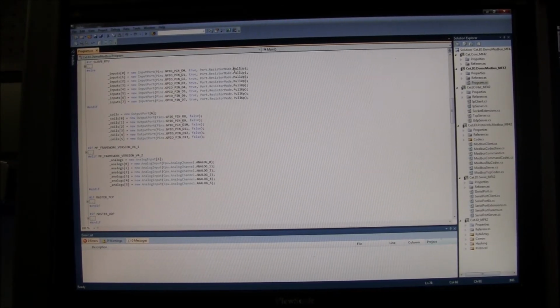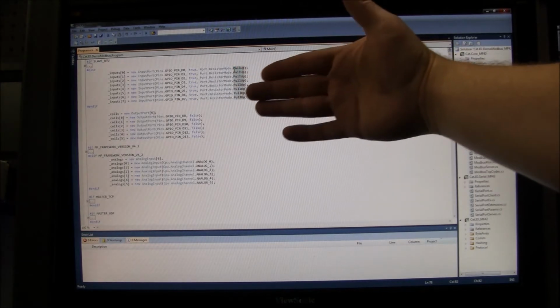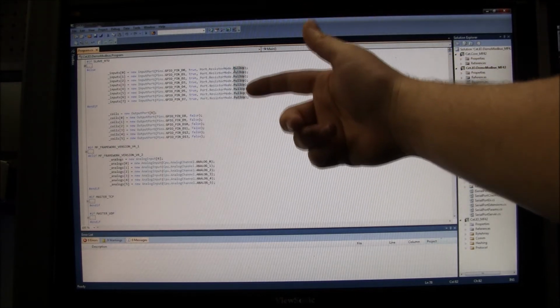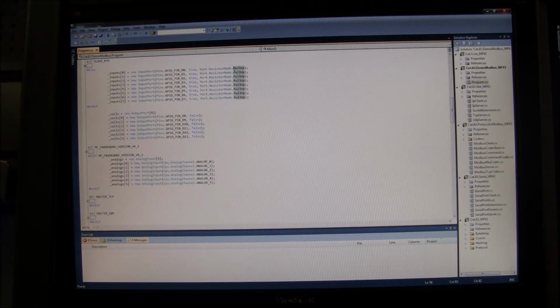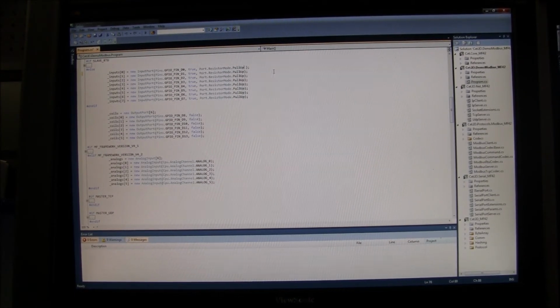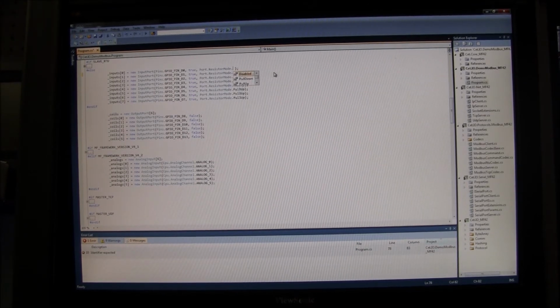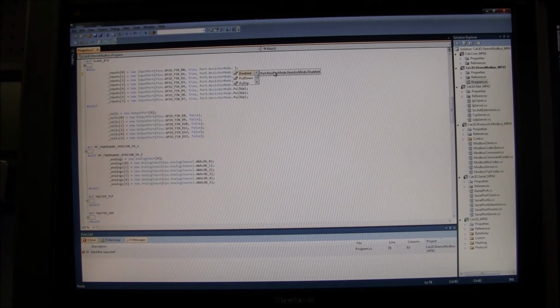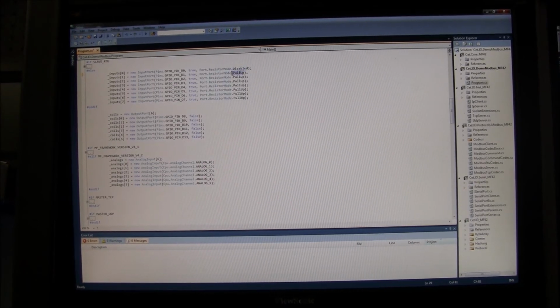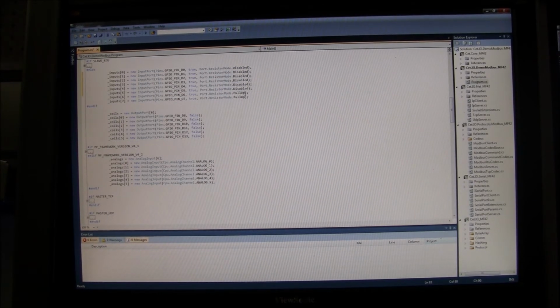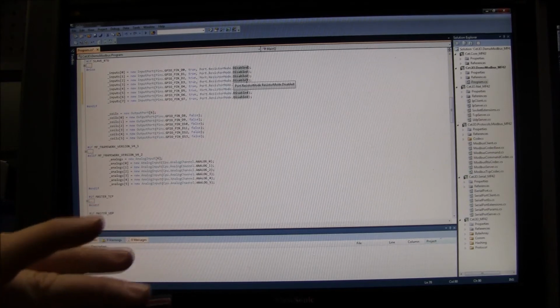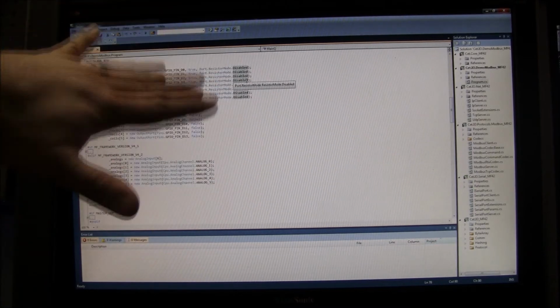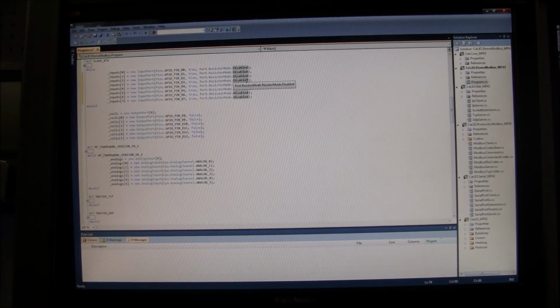Okay, so the issue I was having where everything was on and didn't turn off was these pull-up resistors. And just to show you what you can do, you can go back here, put a dot, and you can have it pull up or pull down. For my situation, the best way to get everything working was to be disabled. The I/O is floating. If it's disabled, it's just going to float. It can actually turn on and off all by itself.